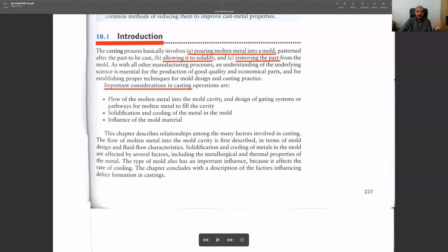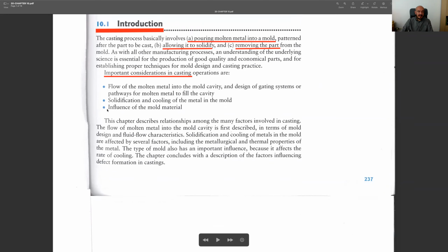So for that purpose, you need to have proper designs and you need to have pure material without any inclusions. Any kind of dirt is not desired in the molten metal. And lastly, the quality of your molding material is highly important, whether you are using sand particles or wood, as they all affect the overall casting process.